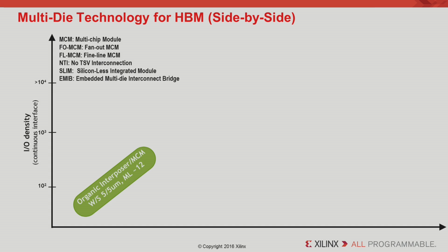Whereas if you take a regular flip chip substrate, for example, the finest metal pitch could be 20 micron. You get far fewer wires, right? So there are a whole range of technologies that are trying to fill this region. If you take HBM, such as a 4-high stack, you could need up to 2,000 wires for interconnecting the PHY in the SoC to the PHY region in the HBM. That may push towards 4 micron metal pitch or finer with multiple layers. So let's start looking at the options here.